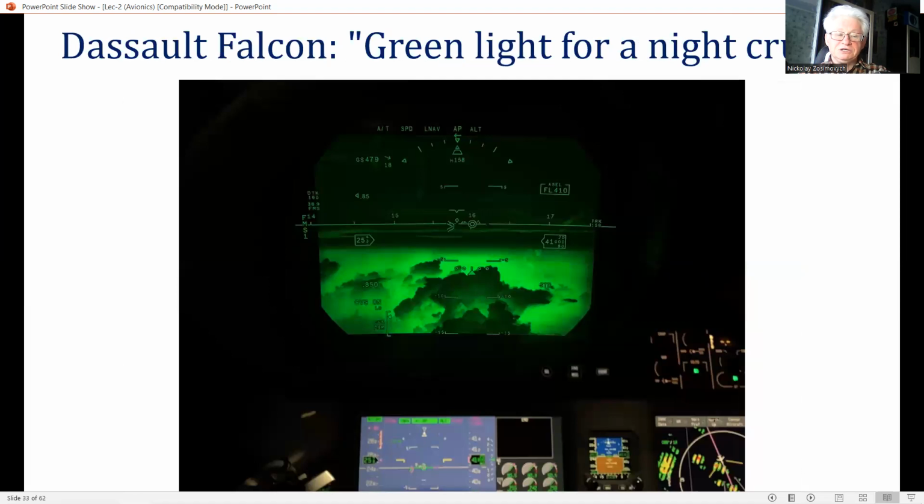Holographic HUDs use reflection holograms, which depend for their operation on refractive index variations produced within a thin gelatin film sandwiched between two sheets of glass. This is really a diffraction grating, and hence a more accurate name for such HUDs is diffractive HUD.